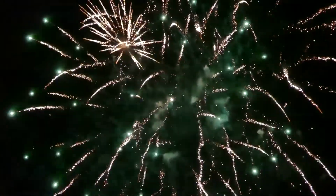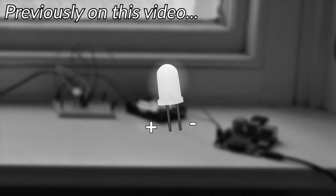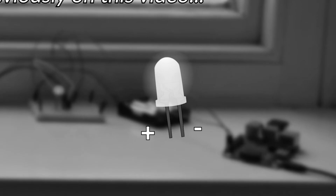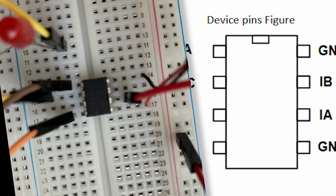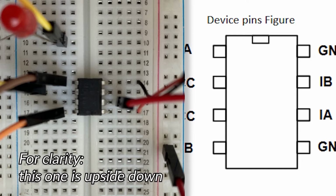This was a big moment for the project because then I remembered I'd got the legs of the light the wrong way round, like earlier when we were doing the prototype, right? And I wondered to myself, have I put the wires into the motor driver right? The answer was no. Because of the way the motor driver is aligned in my breadboard, I'd got my perspectives mixed up and plugged the input and output from the battery in the wrong place.